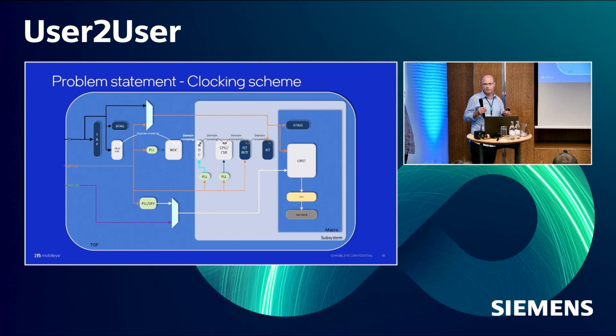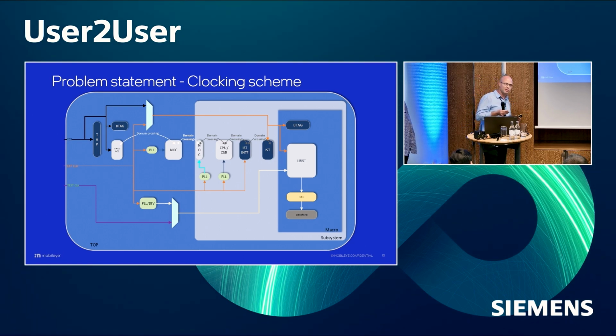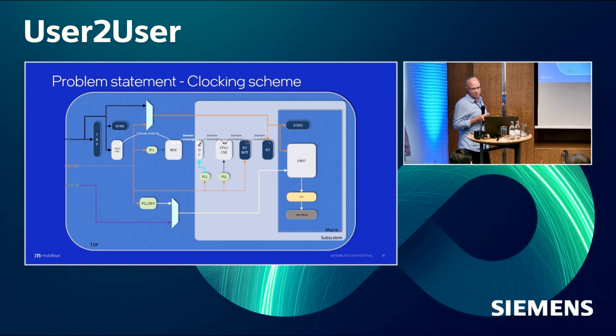It's already crossing the boundaries from your standard DFT logic and test logic. If you think of scan, MBIST, you don't need to test your test logic during production. If your scan logic is broken, all your scan tests will fail. If MBIST is broken, the same. But when you talk about mission mode logic, there is more to it.